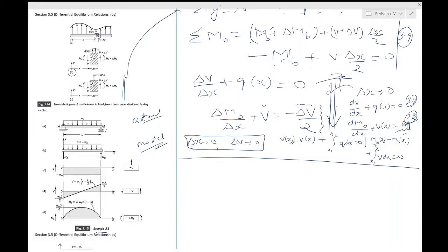By the same logic, because you don't have a frictional force over here in the x direction, similarly there is no point in considering a horizontal force over here, because there is nothing on this side, it would be 0 for equilibrium. So you don't want that. Okay, so the free body diagrams are shown in this 3.15b, and the reaction B is directly vertically upwards.